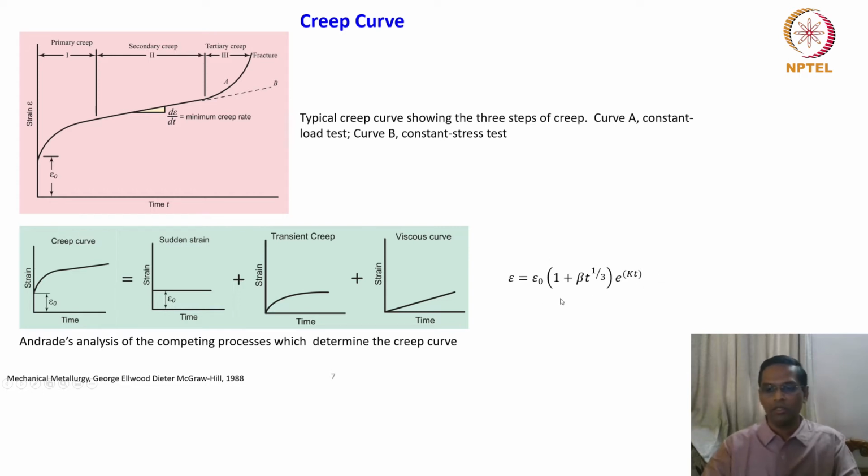In this equation, if k, which is the increment per unit length for a constant strain rate, becomes 0, then the transient creep will be exhibited by beta. So that is one way of looking at it.